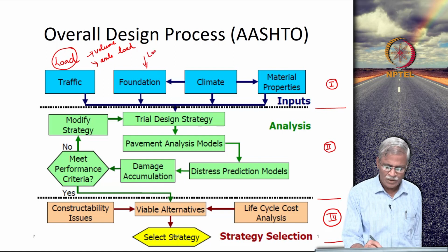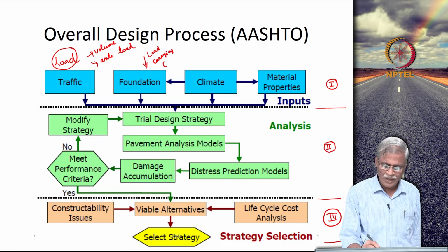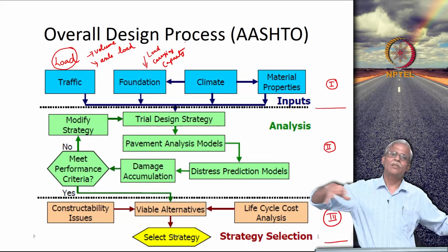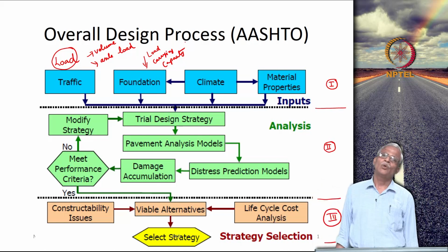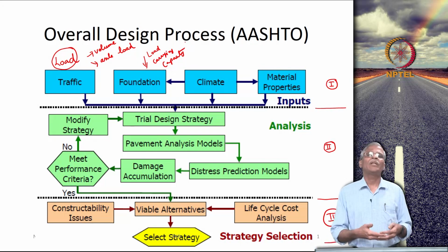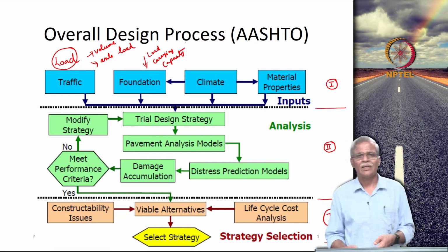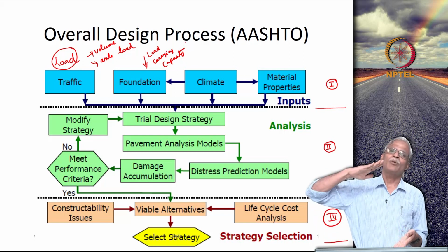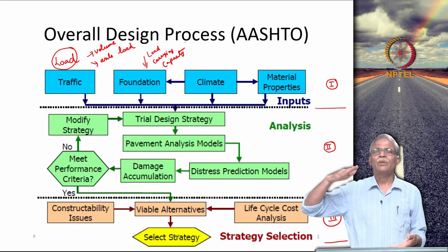You can say the load carrying capacity, and this is where you will also be able to relate to what is called a compacted subgrade. So, many of the design charts that are given in IRC 37 talk about the thickness to be provided on top of a subgrade having 10% CBR.